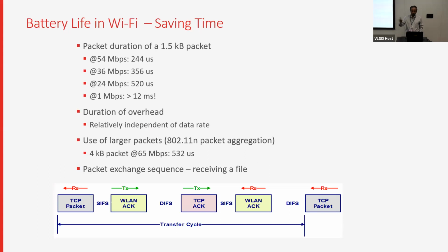So how do you alter data rate? In digital communication, you do it by changing the modulation scheme. Instead of using BPSK, you can use QPSK, or 16 QAM, or 64 QAM, or 256 QAM, or 1024 QAM, or 4096 QAM, which is coming up in Wi-Fi 7. The higher is the number of data possibilities in one symbol, the closer is one data to another. So you need to have very good signal to noise ratio.